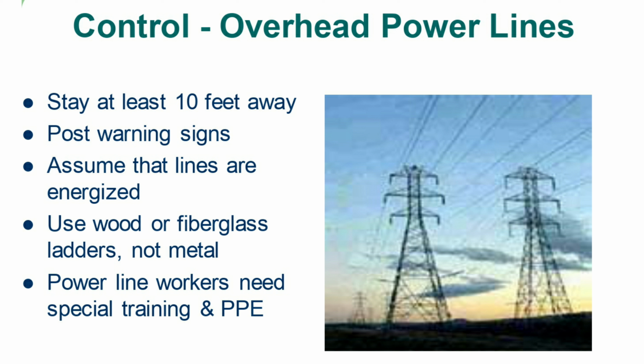Control: overhead power lines. Stay at least 10 feet away. Post warning signs. Assume that lines are energized. Use wood or fiberglass ladders, not metal. Power line workers need special training and PPE.